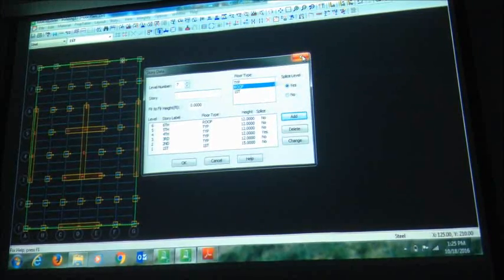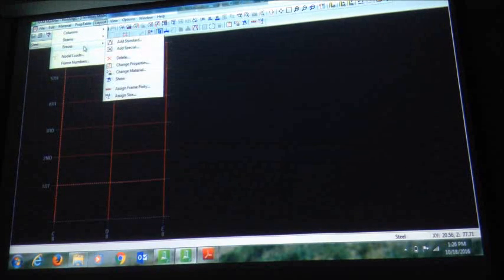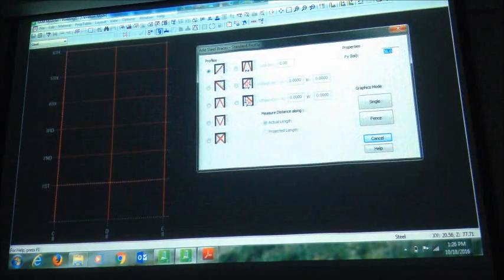Okay, now I need to define my braces here. So as I mentioned, the braces needs to be defined on an elevation view. So click on the elevation, and click on this one, it will come up like that. Now I need to define braces, so if I say go layout, now braces, these are not horizontal braces, these are vertical braces now. And if you can use standard ones, these are commonly used. If you add, you can have this one, inverted V, whatever you want.